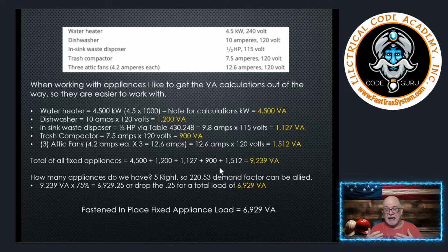Now, the reason I do that is because when I'm looking at the answer in the exam in the end, and you've got 4 different options, A, B, C, or D, I want to quickly be able to see the mindset of whoever wrote that question. Because you can't guarantee how they're writing it or whether they believe in the rounding or in the full value. But also, it allows me to make sure that you learn that if I ask you a question about the actual neutral contribution for any specific circuit, you know what I'm asking you for, okay? It's not going to make a difference in the load calc, though, and you'll see.